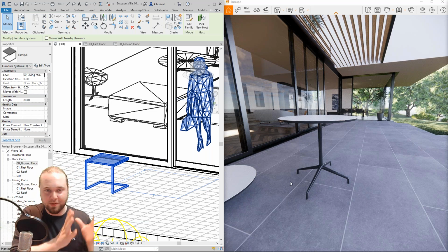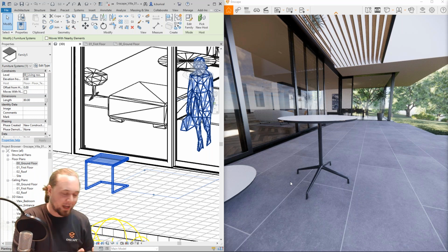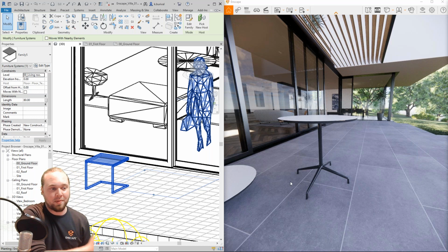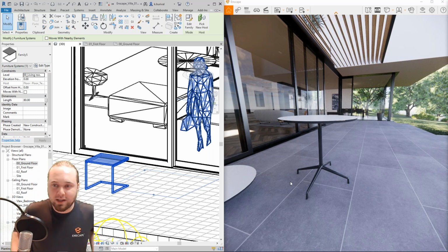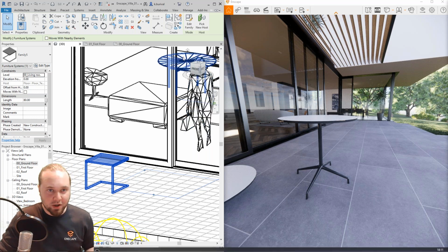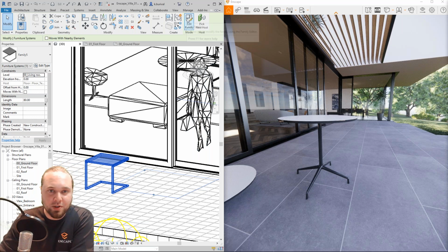You can have the functionality on the Revit side, really just a simplified drawing if you want to, like a circle holding the BIM information of a table, a light, something like that. But you can really keep it simple on the Revit side, and let it be replaced with an Enscape 3D asset inside of Enscape, just by clicking those three dots we mentioned before and choosing a Revit family to replace it with.